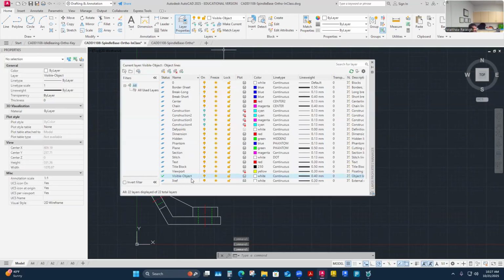This is just me. I make a copy of this and then at the end of the layer name I say it's visible object, and I say it's clipped in view, or I make a little note at the end for my layer. I don't delete it so it doesn't show up on my viewport. I just move it to a turned off, non-printing layer. And sometimes it's just a copy of my visible object layer that I call visible object clipped in view. And so then I know, if I turn that on, it probably matches up with all my construction and where I built the thing.